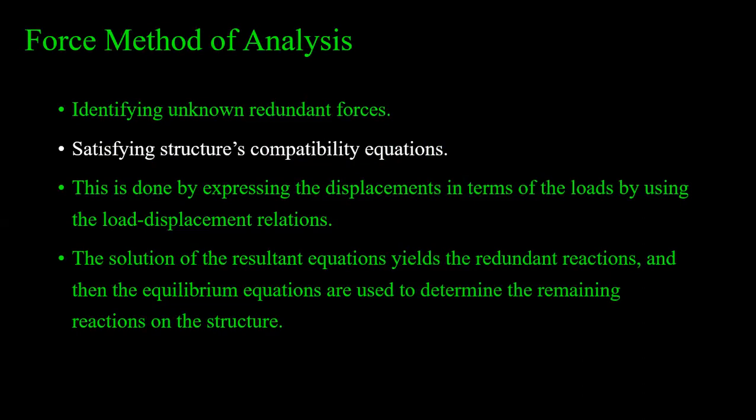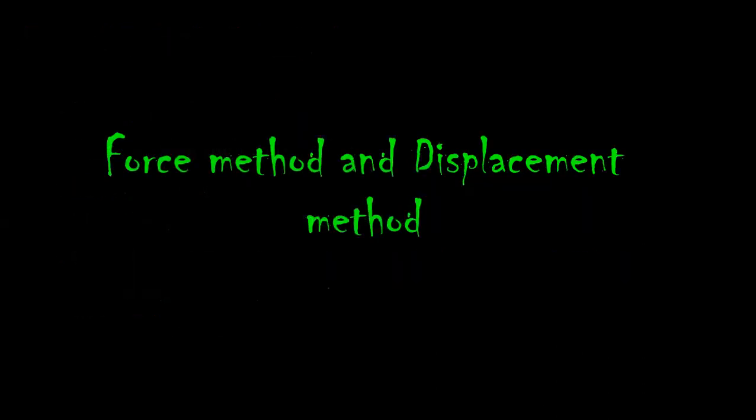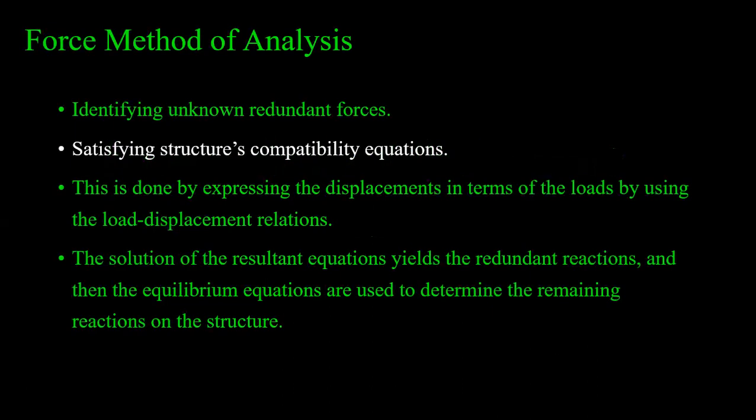What is compatibility? That means the shape of the structure, the shape of the original structure. So we identify the redundant forces and remove the redundancy by making it determinate. Once the redundant forces are solved, then we solve this entire system.